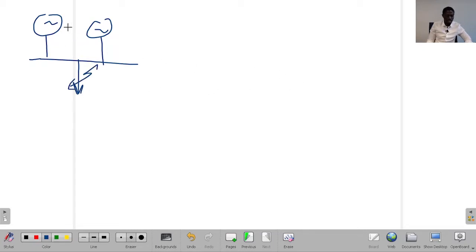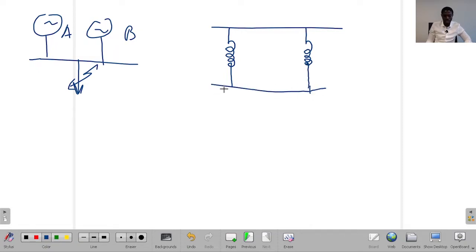So in this case, this is our A and B. We can then create what we call the reactance diagram, meaning that we've got the reactance from generator A and the reactance from generator B, and these connect together and meet at point F. So this is the reactance which we calculated for B, 87.5%, and we've got the reactance here at A, which we had calculated at 70%.